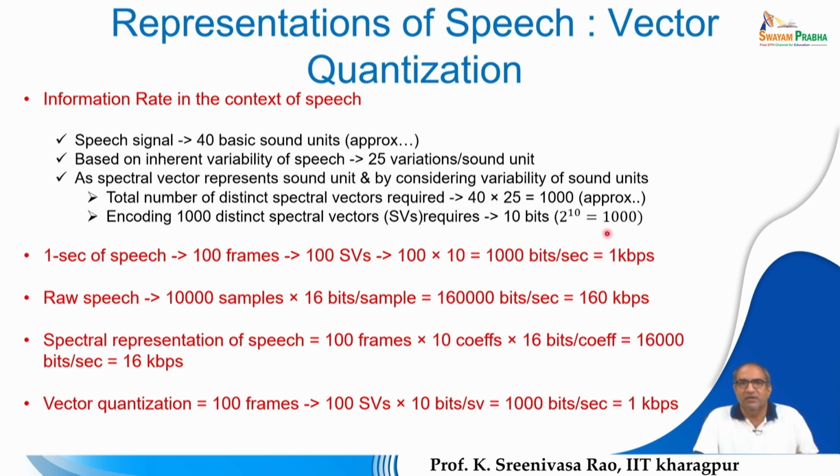This is very similar to the case of an analog signal, where your sample amplitudes vary from plus 10 volts to minus 10 volts, right. If you take a real amplitude, there are infinitely many possible real amplitudes between plus 10 volts and minus 10 volts, but we cannot represent that. So, this range from plus 10 volts to minus 10 volts is split into, for example, 20 levels or 30 levels or 32 levels, where each step will be something like 0.5 volt or 0.3 volt.